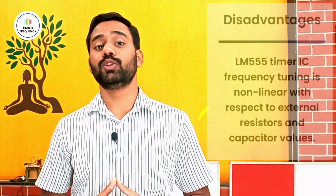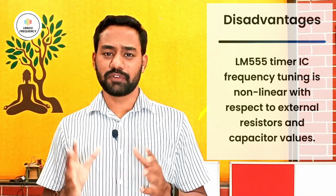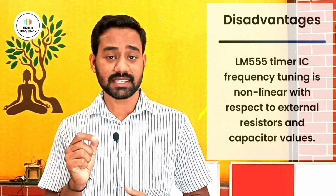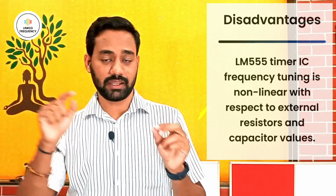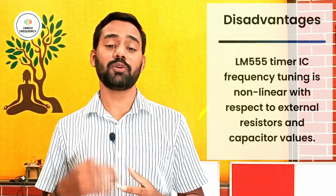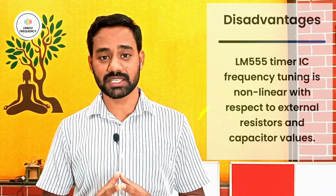Now let's talk about the disadvantages of this particular IC. First one is the non-linear behavior of pulse duration or pulse width. The frequency setting of this IC is not linear. Though it is precise, it is not linear. By changing the resistance value and capacitance value, you cannot say it is a linear curve by just using a mathematical curve formula. You have to experiment and calculate it with a proper formula to understand what frequency you are generating based on the resistance.